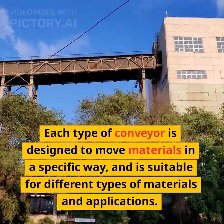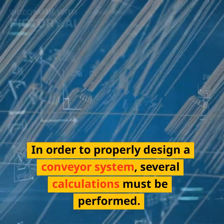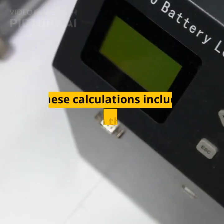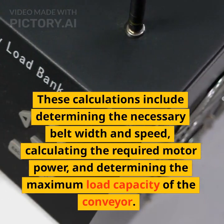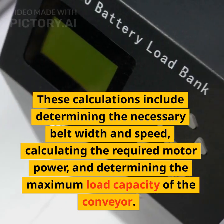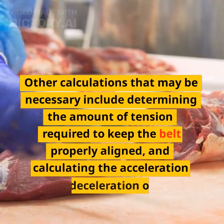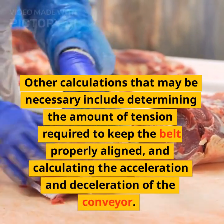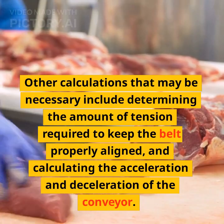materials and applications. In order to properly design a conveyor system, several calculations must be performed. These calculations include determining the necessary belt width and speed, calculating the required motor power, and determining the maximum load capacity of the conveyor. Other calculations that may be necessary include determining the amount of tension required to keep the belt properly aligned, and calculating the acceleration and deceleration of the conveyor.